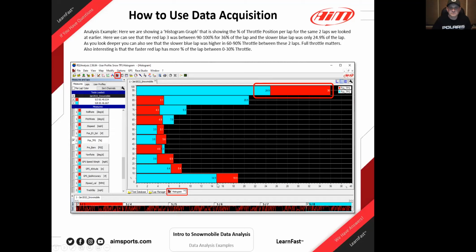And then the one at the bottom is always interesting to me too. When everything is working right, you can either be on it or you can be off, right? And maneuvering the snowmobile. The fastest lap actually got 18, almost 19% at 0 to 10, where the other rider is at 15%. So there's that 3 or 4% there that kind of shows that the red faster lap was either wide open or off the throttle and maneuvering the sled to do what they want with it.